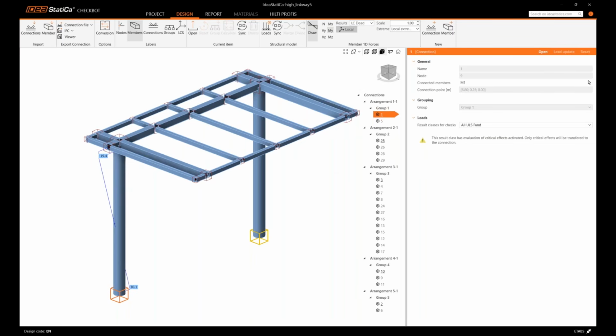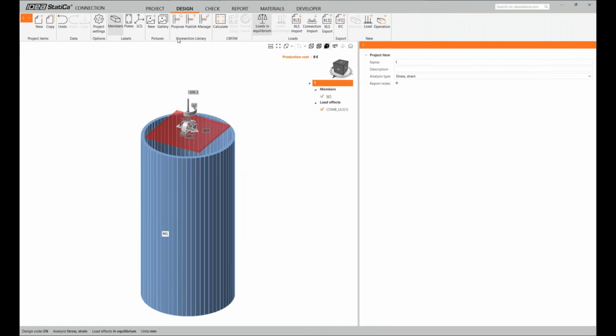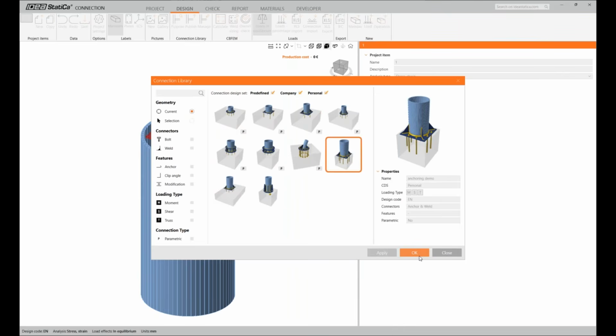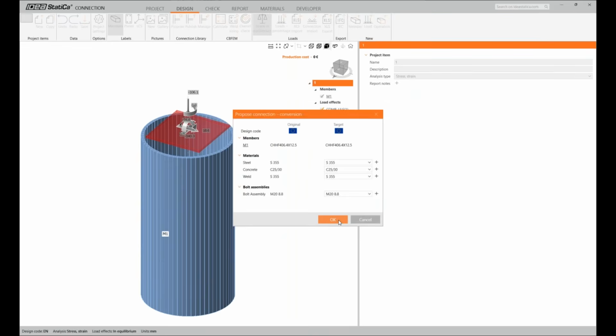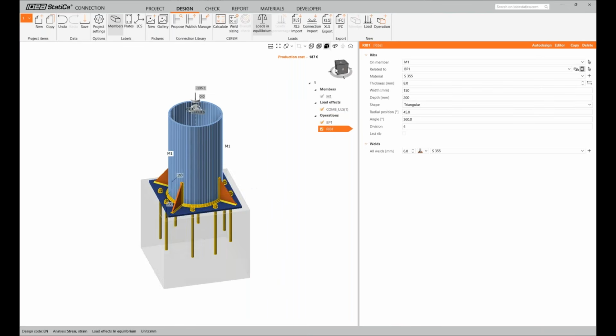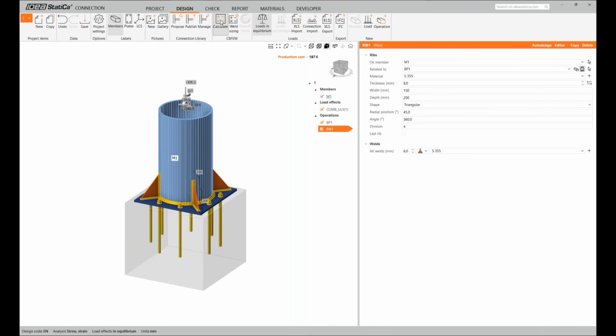It's also opening on my other screen, so I just bring it over. All right, I prepared a template for this, so I just click propose to put back my previously saved templates. For this case, because I'm only modeling the part of the concrete block, just the stump, I then click calculate to check whether the anchor fails or not.